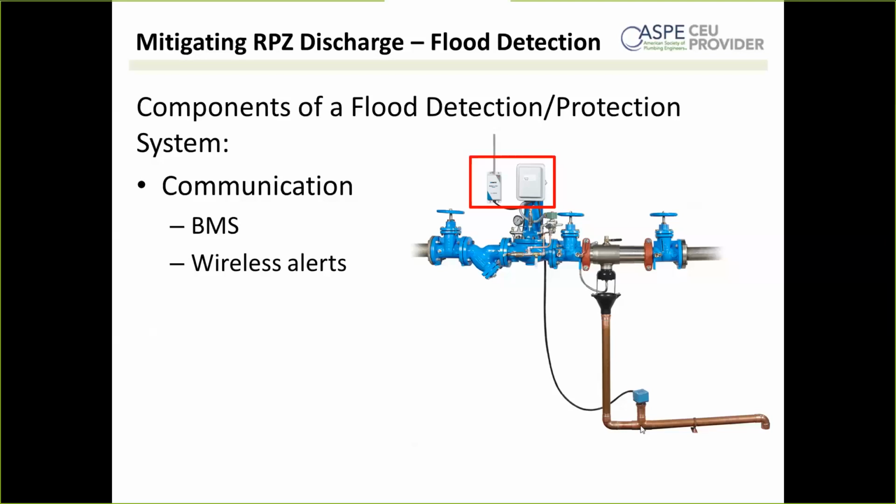I know that's not always possible given time restraints, space restraints, money restraints. You know, strainers aren't free. But I will say, you have one big one on the backflow, that's going to have relatively large openings, because you're going to want a fair amount of flow coming through that backflow preventer because it's servicing your entire building. Your smaller backflow preventers, whatever strainer you get with it is going to have smaller openings, so it's going to increase those levels of protection. So I'd love to see a strainer in front of every backflow personally.